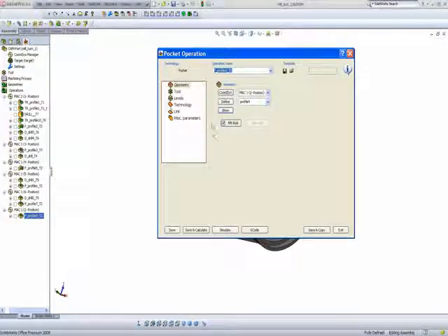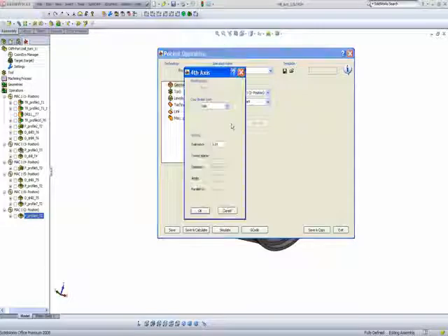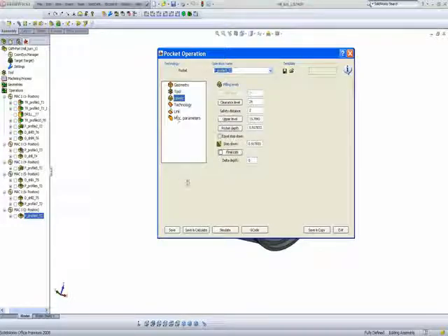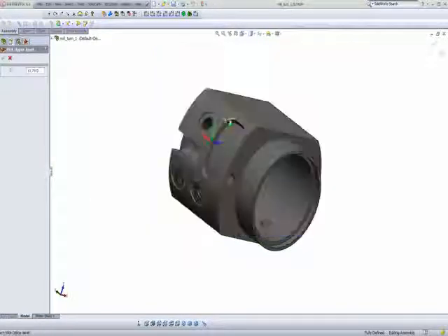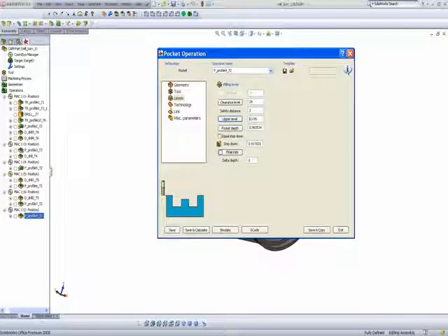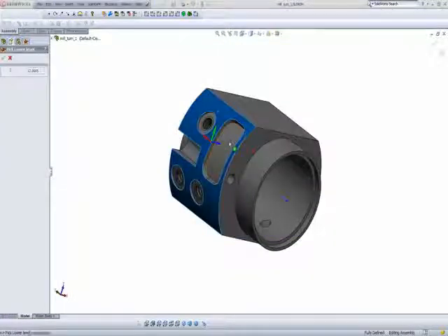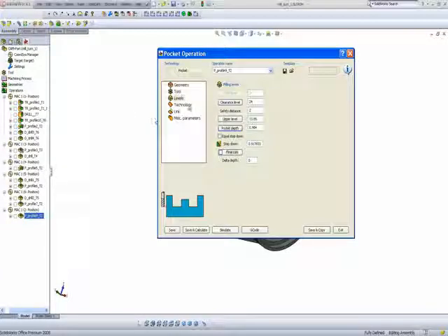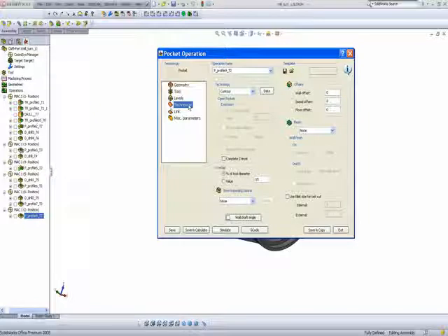So we have now the option over here on the bottom called 4th axis. If I were to open it up, you see we're working on a wrap. Like I said, we wrapped around, and we're wrapped around the x-axis. Now the tool that I will be using is a 2.5 millimeter tool. My upper level, to do the upper level, all I do is simply click anywhere on the outer surface. And my pocket depth, all I do is click anywhere on the floor of that pocket itself. My technology is the same as any technology in any pocket that I have.